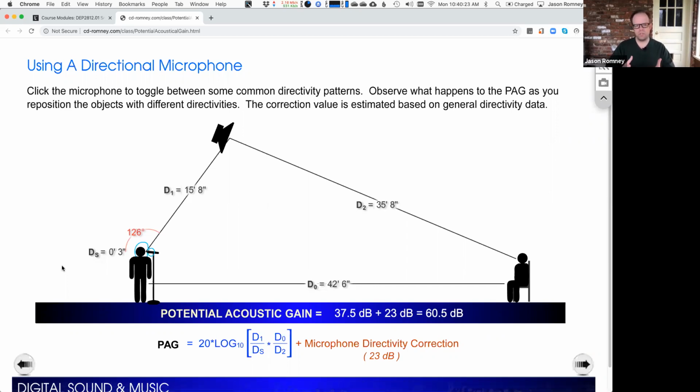So some strategies for dealing with that: when I'm doing a show, I will almost always put in low pass or high pass filters on all my mics that are live on the stage. Sometimes all the way up to 120, maybe 200 hertz, because for most voices, there's just not a lot of information going on down there. And that's where the microphone is omnidirectional anyway.